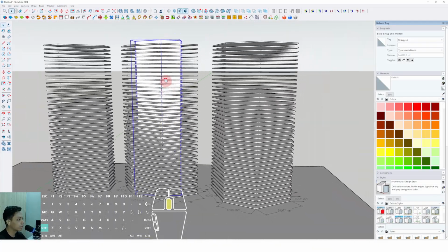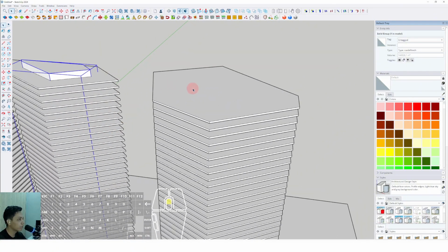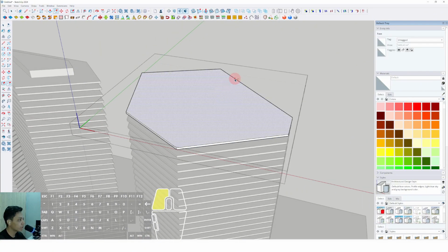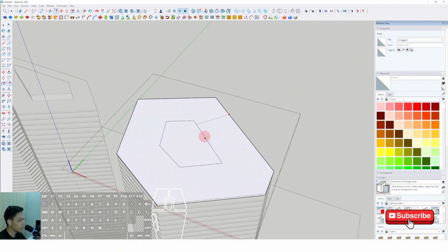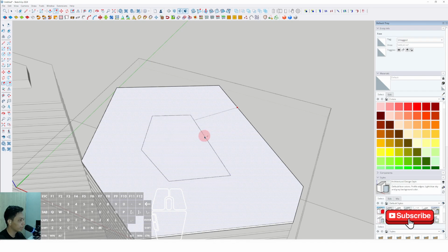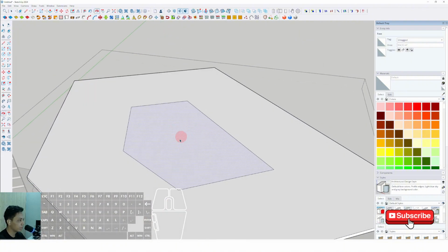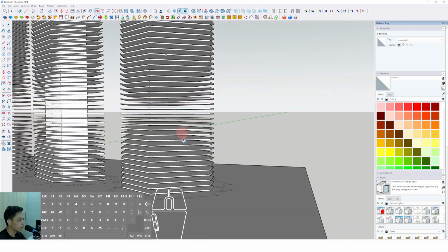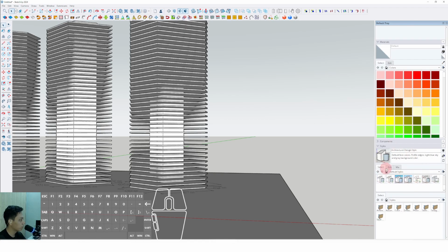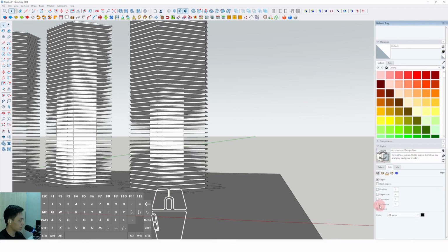Okay, and we get this core building design. Also for this one we offset it inside around 12 meters, or maybe it depends on the proportion of each building floor. So we can offset this one inside around 22 meters, enter. Then we click this plane and select edit, copy. Then exit from the group, paste in place, and push it until this position.